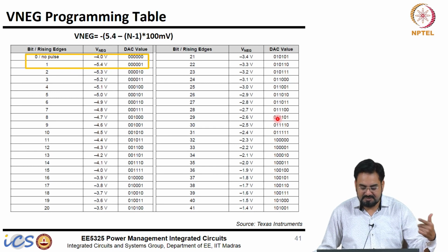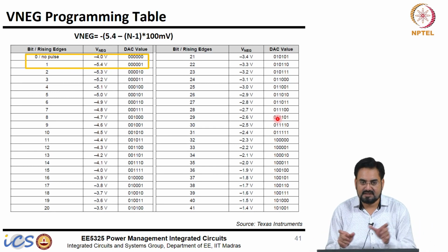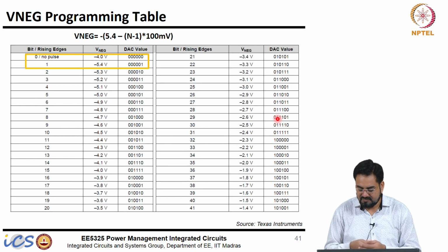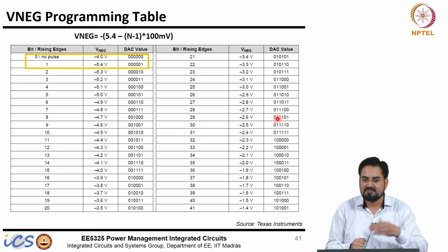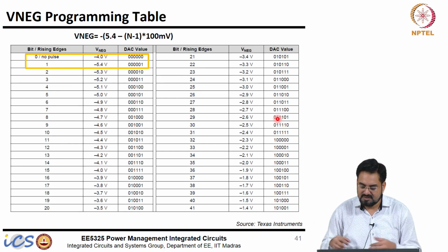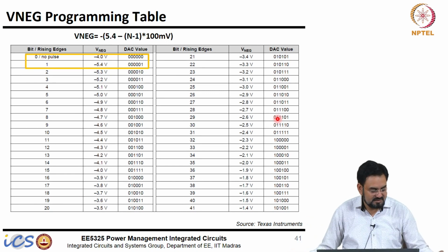These pulses will be counted and then latched, and we know that these voltages can be programmed using a DAC. So let's say if there is a feedback resistor, you can just program the feedback resistor and get different values. Those will control these voltages, that voltage DAC or resistive DAC, whatever, or you can change the reference also if you have.